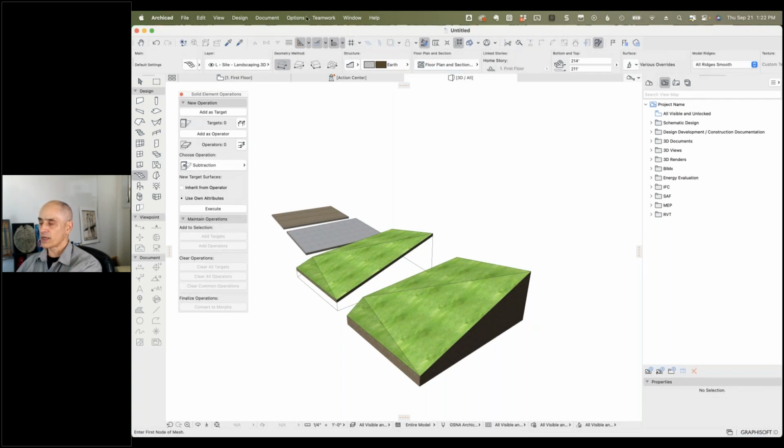Let's look at the mesh to roof tool, and I don't know if I have it loaded right now or whether it is automatically loaded. Is that a goodie now, or does it come standard? Mesh to roof is considered a goodie. So a goodie is an add-on tool in the ArchiCAD environment that Graphisoft provides. Goodies in general have been around for 15 years, at least since ArchiCAD 7 or 8 or something like that. They extend the functionality of ArchiCAD, but generally Graphisoft says they're limited functionality. We haven't put it into the main program, partly because we don't want to put in the effort to make them perfect, but if you find them useful, go ahead and use them. So they say they're goodies, they're optional.